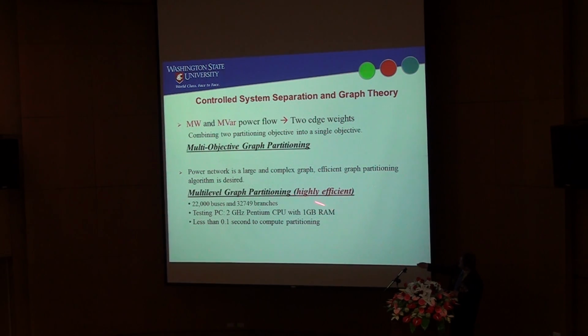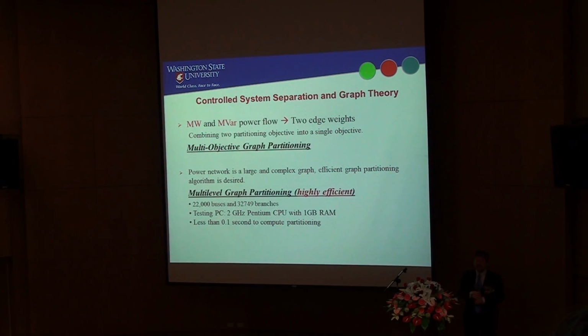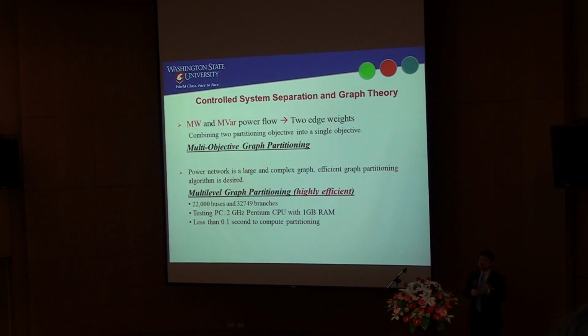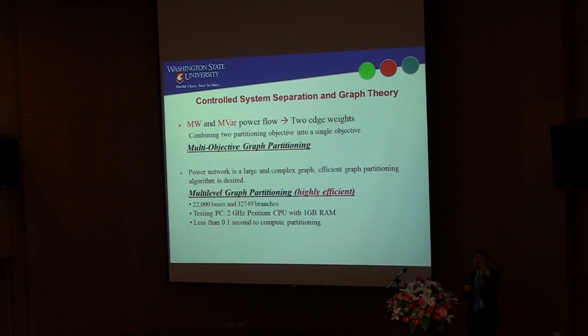Why do I need partition? Traditionally we use a special protection scheme, SPS, and SPS is for very specific scenarios. So I look at a particular line, a particular relay. If a particular scenario occurs and it meets all the criteria, then the relay trips the breaker and the system is split. That's SPS. But when you look at the defense system, it has to be more general. It has to be smarter.